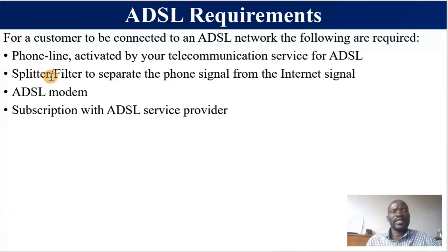Also, a splitter is needed to separate the voice signal from the internet signal. This is a requirement if the customer wants to have voice and internet access at the same time. If he doesn't want to have the two at the same time, then this is not a requirement. Also, please take note that an ADSL modem must be installed at the subscriber's premises. This ADSL modem has got a lot of functions.